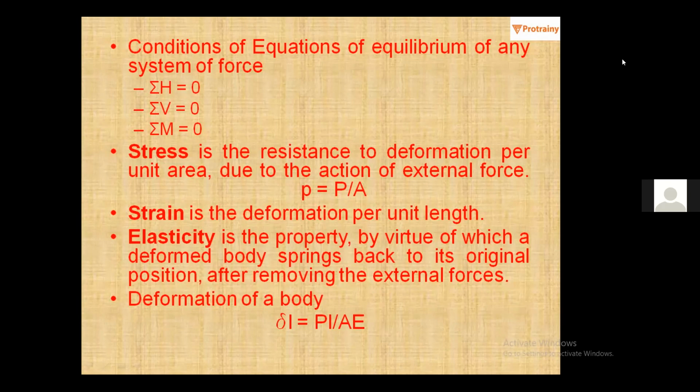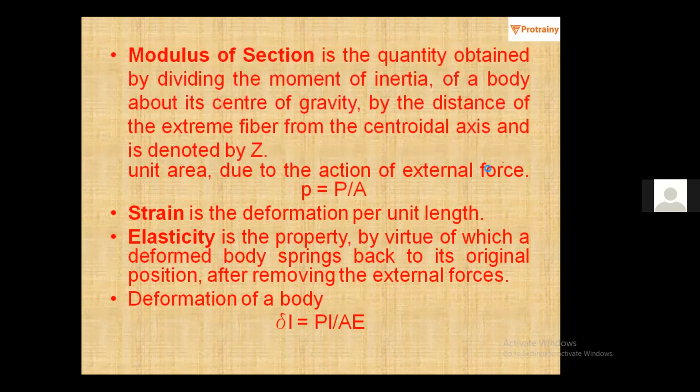Now what is delta L? Delta L is deformation of a body, equal to P, external force, L is the length of the body, upon area of cross section, upon E. What is E? Modulus of elasticity. So moving on, this is deformation of a body.